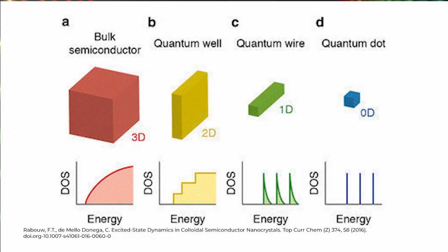To introduce quantum effects into a material, we have to reduce the dimensionality from a bulk sample in 3D, which shows classical effects, to 2D, 2 dimensions, and furthermore to one-dimensional quantum wires and zero-dimensional quantum dots. This reduced dimensionality of an electron pumping device is a semiconducting nanostructure confined into a quantum dot with narrowly etched oscillating gate barriers fabricated on the surface.